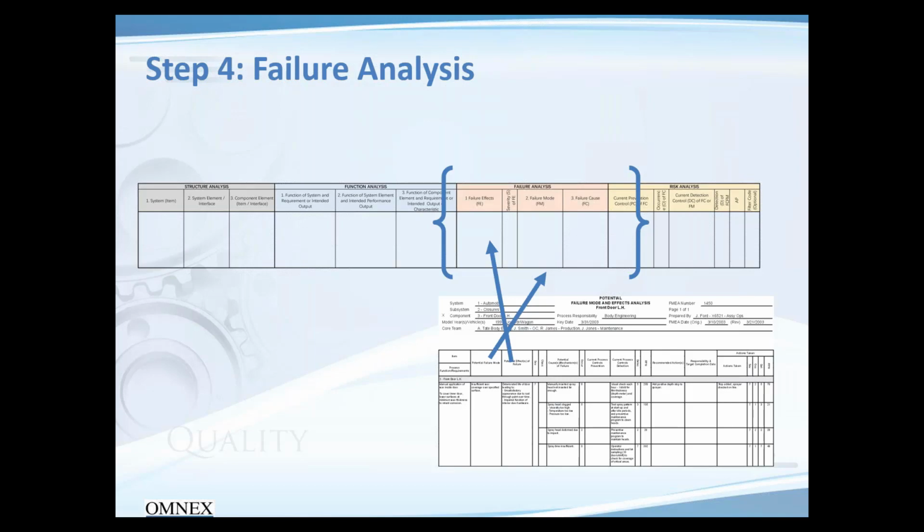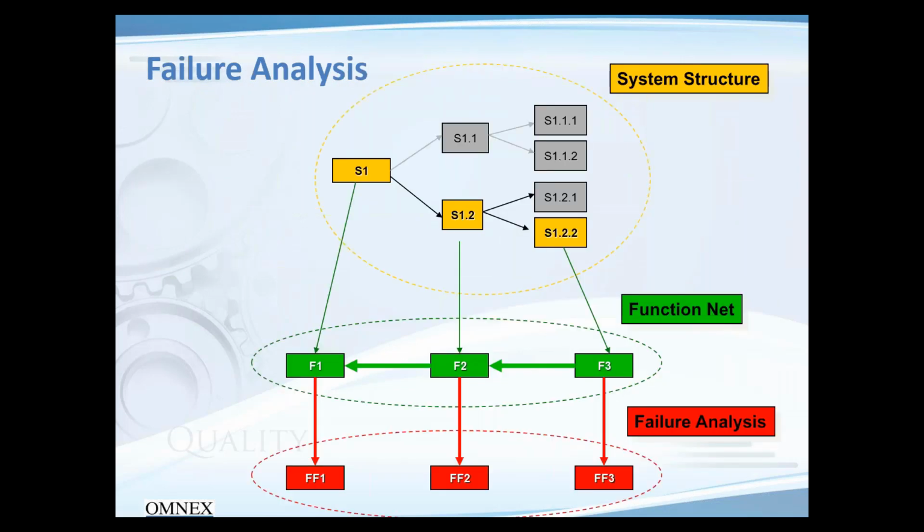So again, if we go to the diagram that I provided earlier, this kind of shows better what needs to be done. First, what you would do is look at what failures you don't want to have at the system level, and then what type of failures could happen at the subsystem, and then what failures you could have at the component level. And then somehow you have to chain how a failure in the component may result in one of those failures at the subsystem level. And then the subsystem level would have to understand how things would fail at the system level.